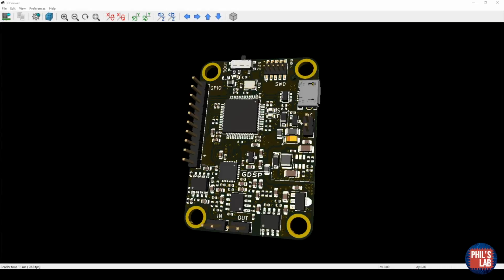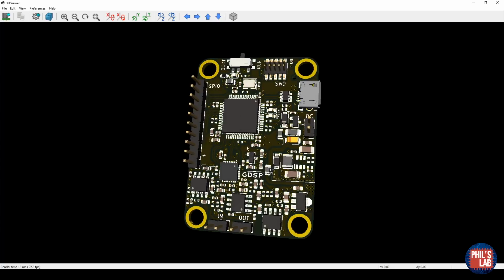One last thing I'd like to add and talk about is the fact that we have these GPIO or ADC inputs which are routed directly to the ADC channels of this STM32 F4 microcontroller. And in the previous videos I've been using these ADC channels to read, for example, switches or potentiometer values to change control settings of various effects on the fly. For example, the filter bandwidth or the volume of my guitar effects pedal.